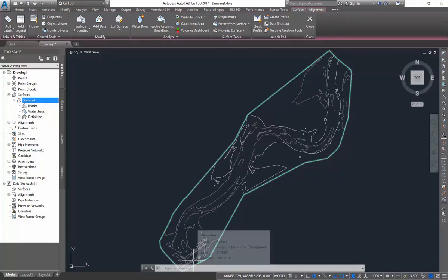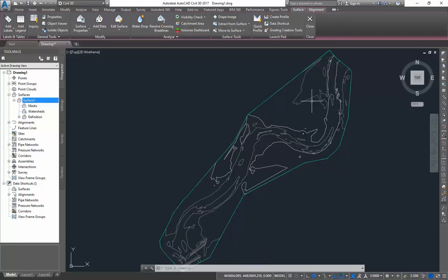And if I look down here at the lower left, I see it's 1,660. So that tells me that the river is flowing in this direction. But while this is helpful when I'm within the drawing and I can pause my cursor, I might want to add some contour labels so that the drawing itself helps with the directions and information about that.